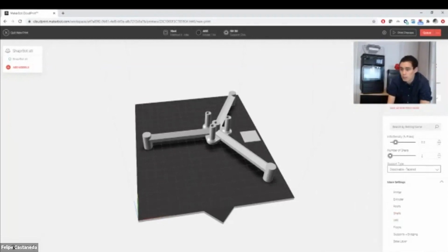And once you've selected either one, balanced is going to give you a nice in between with about 20% infill, a straightforward printing process, and a pretty good balance between the time that it'll take for your part to be printed out and the actual sturdiness of the part.